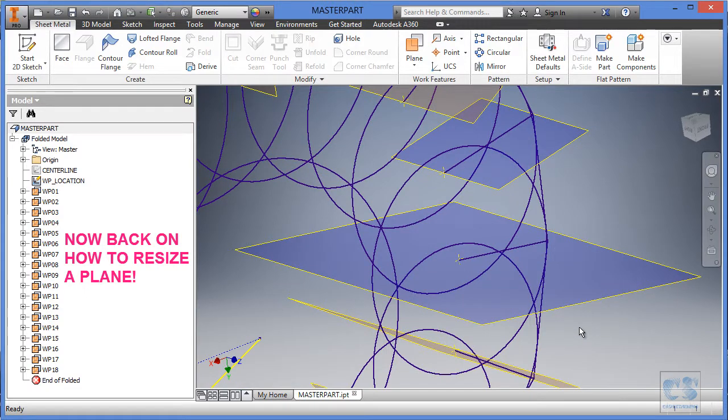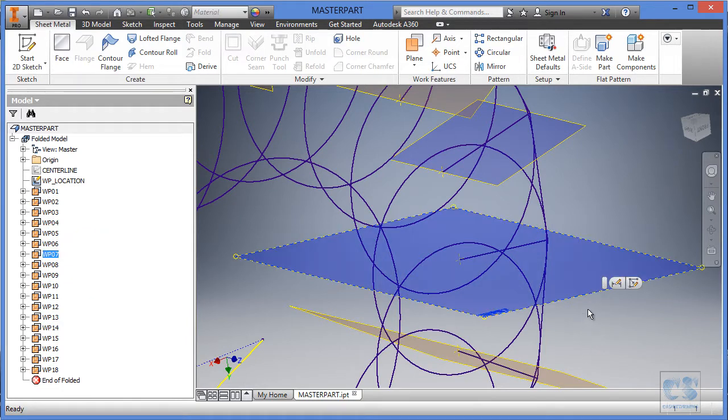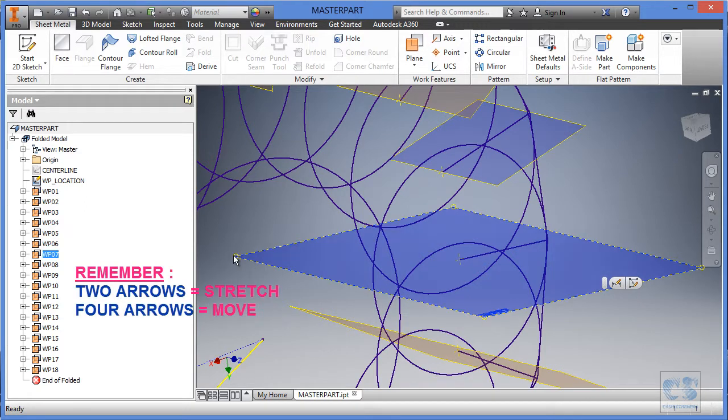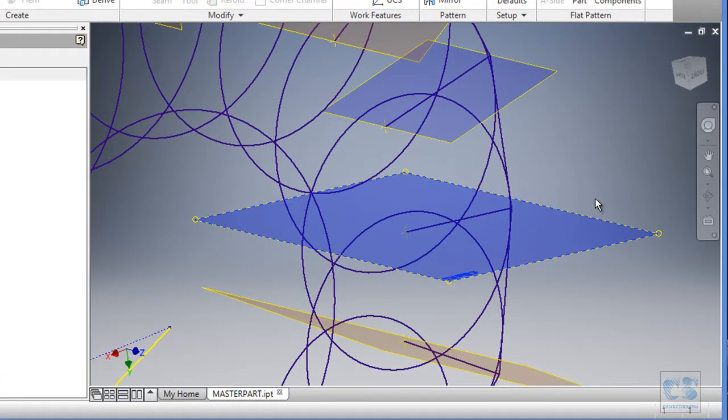This is a complementary video, and I want to expand further on how to resize a plane in Inventor. So what I show in the video is I was selecting the planes and then looking for the corner where I will have this double-sided arrow, and from there I will resize the plane, then move it again to the position where I wanted it. What I found later is that when you have this move glyph near the cursor, if you want to have the double arrow instead, what you have to do is to click once, as you can see. Then I can now resize the plane.